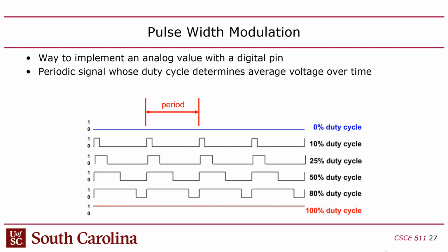Now with regard to audio, if you try to do audio over a PWM signal, which is how Class D amplifiers work, I don't know if any of you are into stereo equipment, but they have Class AB amplifiers for cars and home audio, and then there's the Class D amplifier. Class AB is more of a rectifier, but Class D is actually using a PWM signal. But you can't just run this straight to a speaker, because the speaker will pick up the frequencies from these steep switching edges, right? So if you use a PWM signal to drive a speaker to play music, you have to put a low-pass filter on there to filter out any artifacts you get from the switching, right?